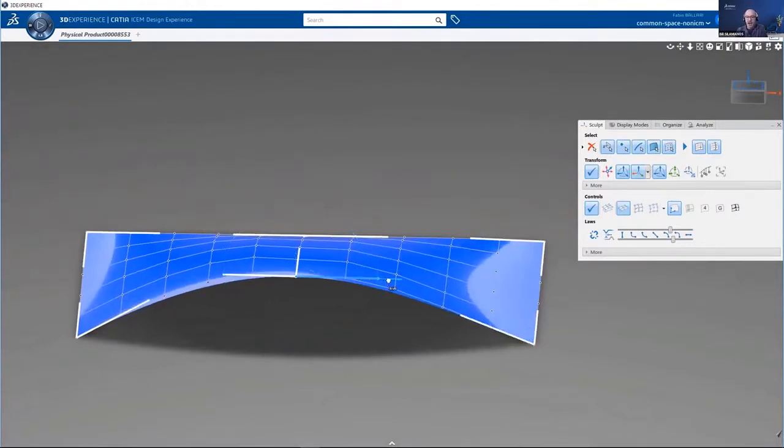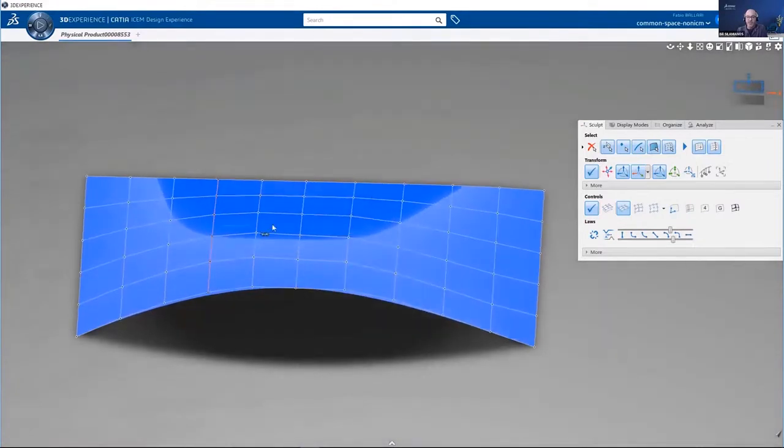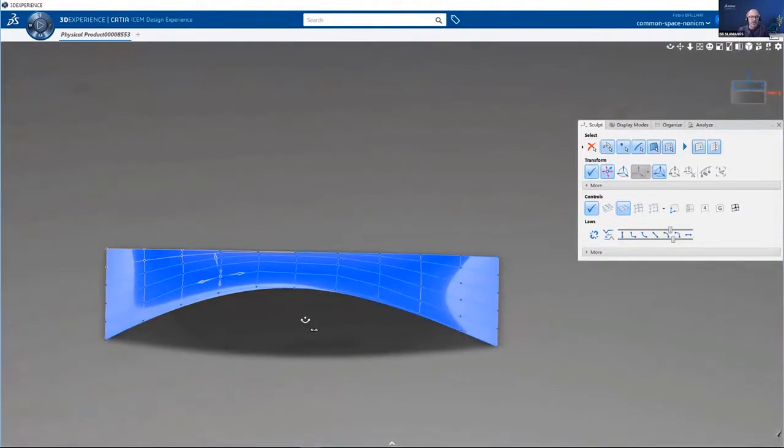As in here, we're going to do some cross-patch modification. Very interesting ways to distribute and slide points back and forth on the sides. And again, this is a very highly productive way to work and deform entities. Here we're using some of the trace commands to use shapes. And again, we're deforming the control points proportionally back and forth, using the associativity and the match to control both sides. Very interesting way to work.